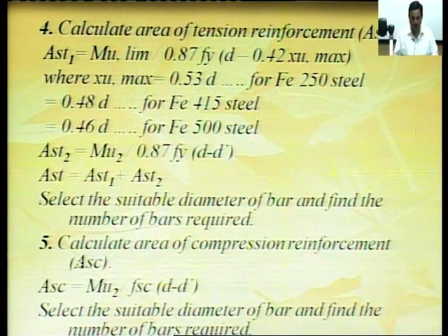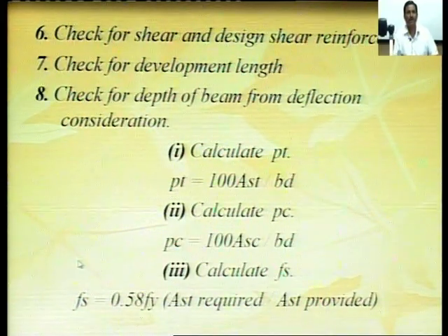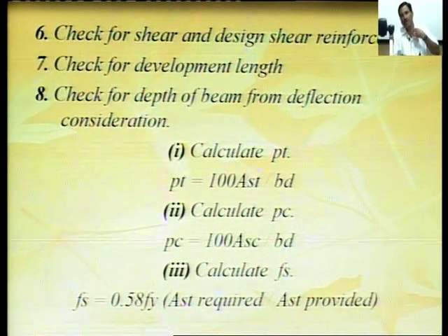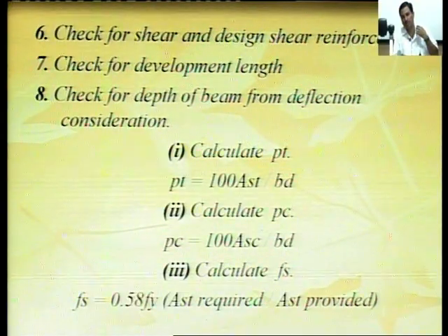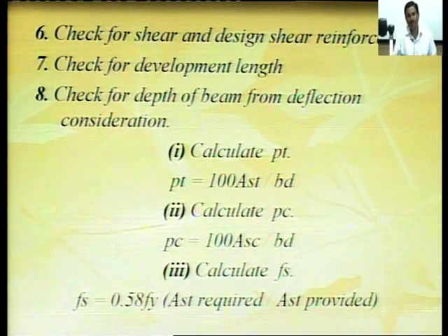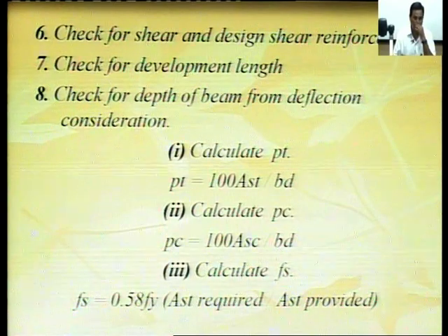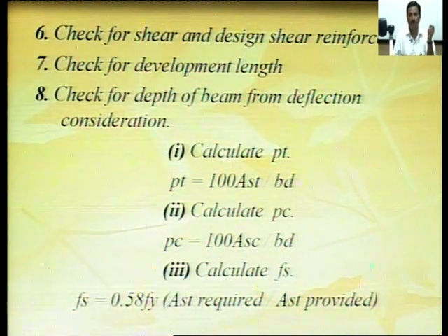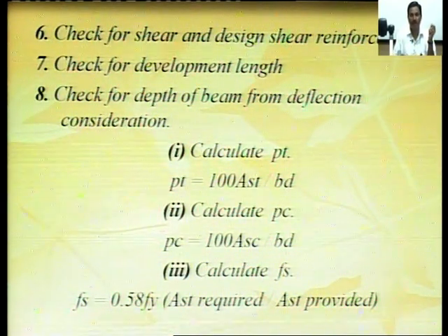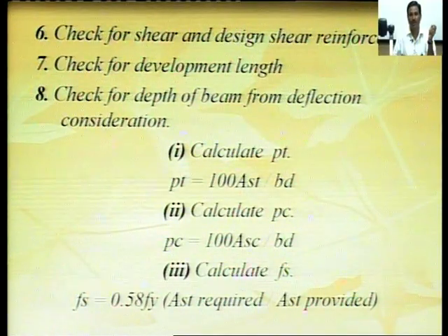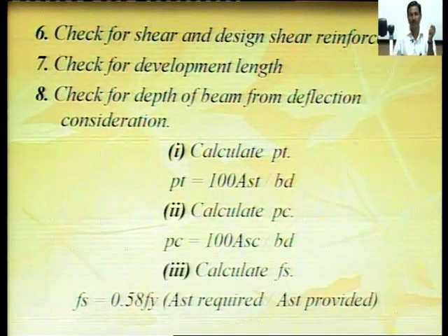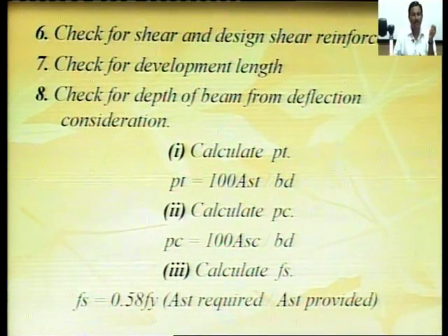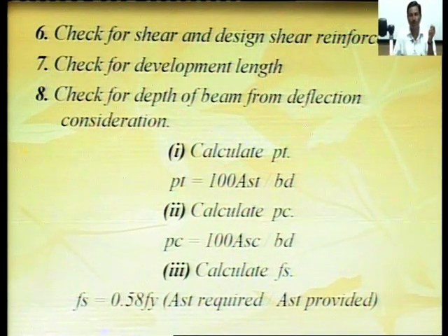Next step is the sixth step, check for shear and design of shear reinforcement. After we decide the area of tensile reinforcement and compression reinforcement, we have to apply the check for shear and design shear reinforcement. In this check, we calculate the shear force and then the nominal shear stress.